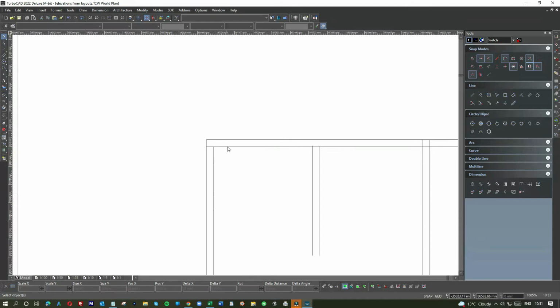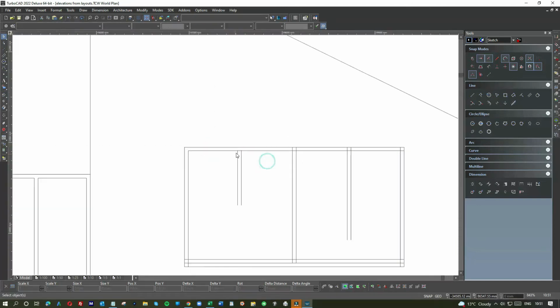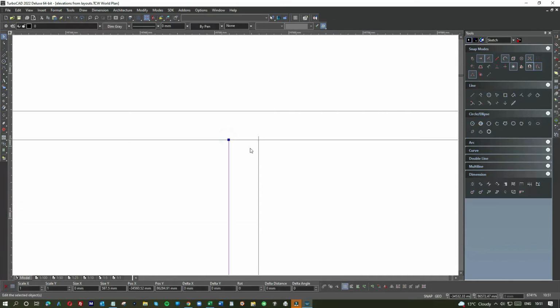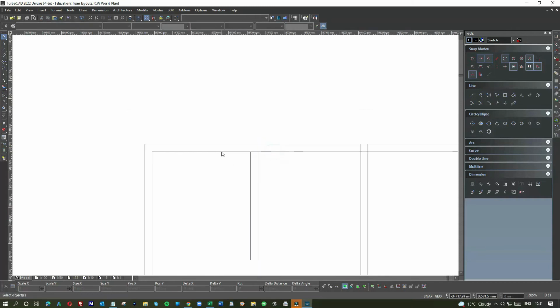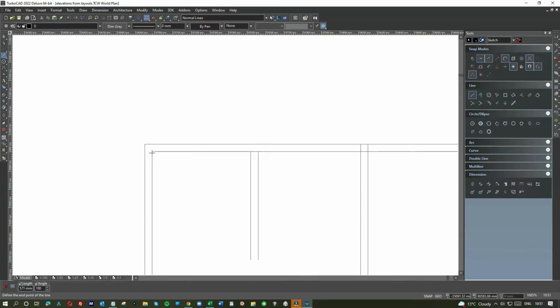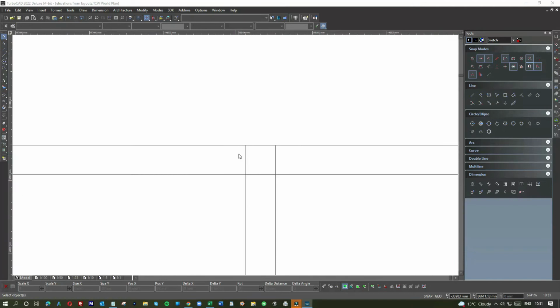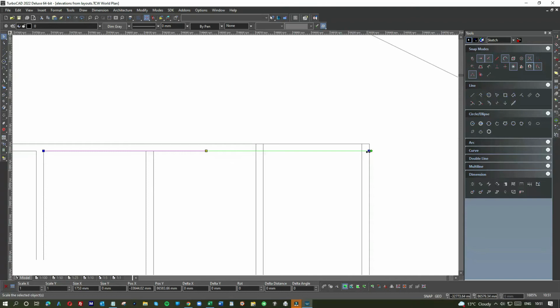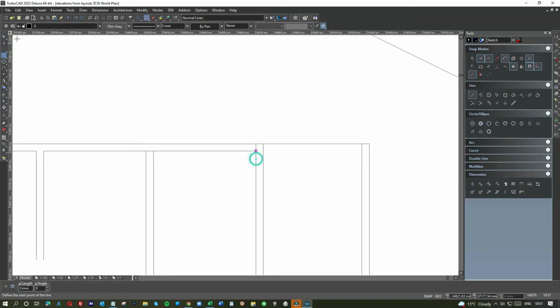Now, on this particular project, I don't need to show you every elevation. You don't have to watch me doing every elevation, because you're not going to be learning much. The main thing is to see me doing one elevation, and then you just replicate. Similar procedure, just follow it. The first elevation is usually the hardest, because you're establishing the floor heights, the slopes, the roof height, etc. Perhaps I'll do an outline for the next elevation, just to show you how much quicker it is because you've already established the core profile. And of course, if you're doing more windows at the back, the likelihood is they're similar heights and similar widths, so everything is quicker on the other elevations.